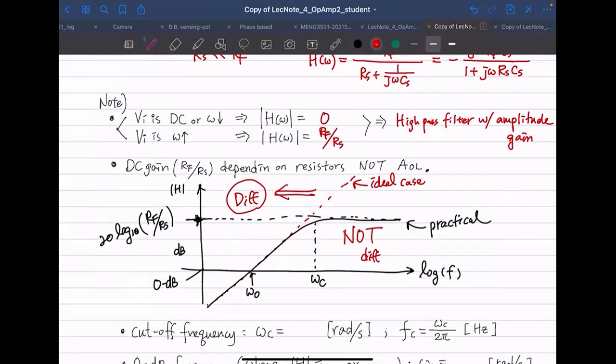And we don't want to go to too low a frequency because the output is getting smaller and smaller than our input as the frequency gets lower. So we're kind of losing power. You provide like 10 volts in, you only get like 0.5 volt coming out. You're kind of losing power, right? So in general, we don't want to use this frequency at all. So we may want to use somewhere between here and there.